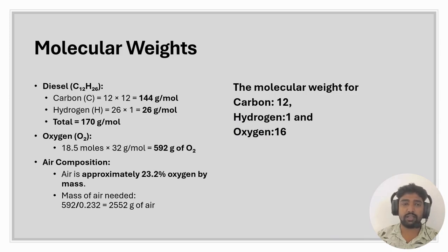Now see here, this is pure chemistry. But in a real diesel engine, we almost never operate at this stoichiometric point. This is important. We almost never operate at this stoichiometric point.